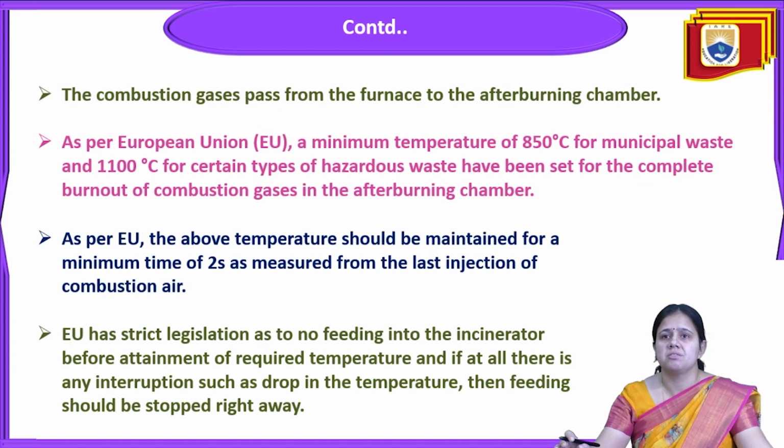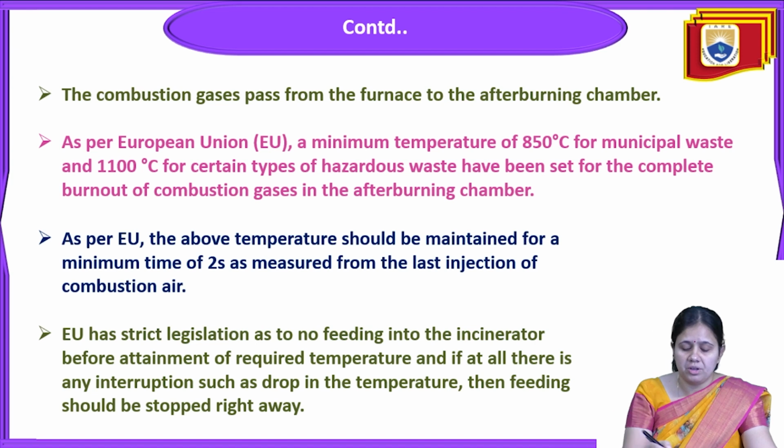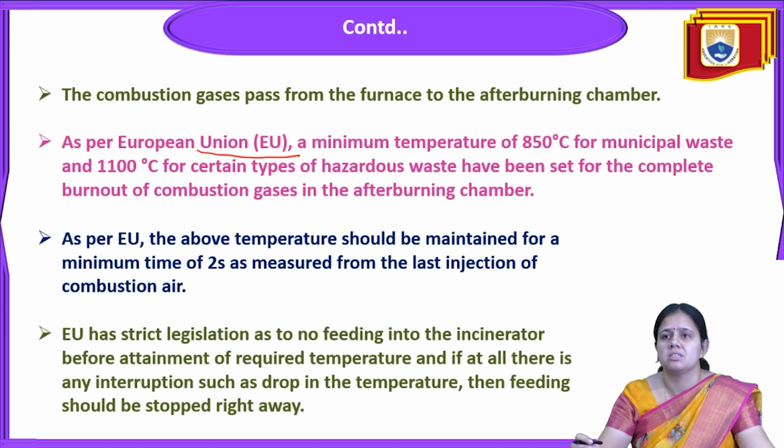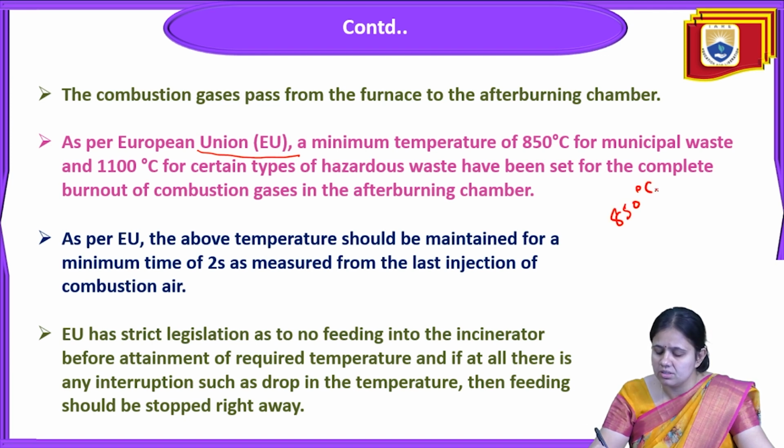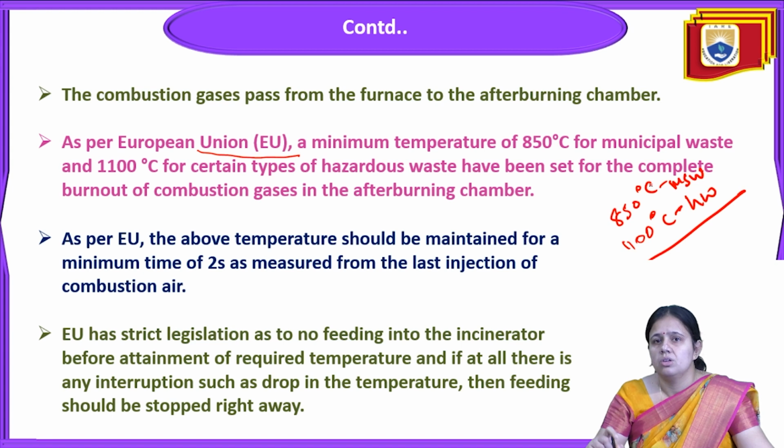The combustion gas passes from the furnace to the afterburning chamber. So from the European Union (EU), a minimum temperature of 850 degrees Celsius for municipal solid waste (MSW) and 1100 degrees Celsius for hazardous waste. Okay, so they have set a minimum temperature.